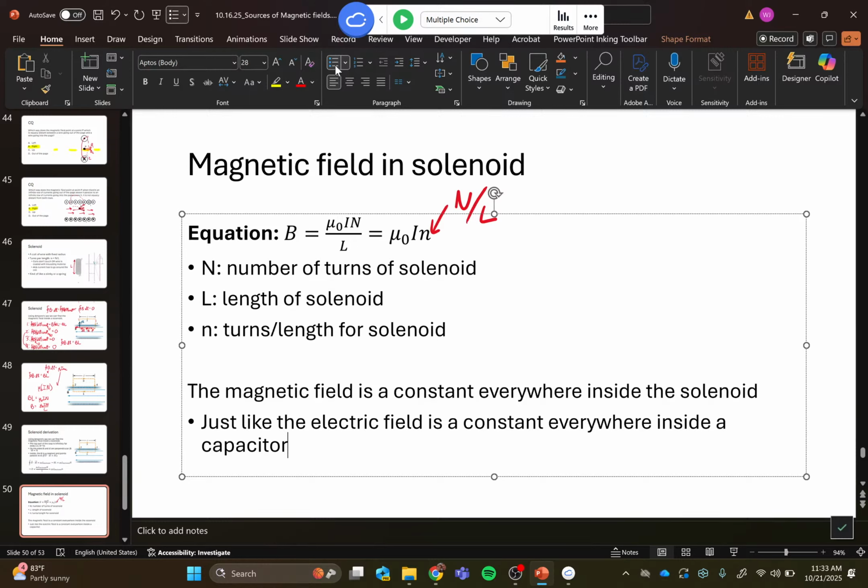Correct. If you all look at these solenoids, if you want to make a strong magnetic field, you take a bunch of loops of wire and you stack them on top of each other. And that is every single circuit. These solenoids are everywhere. Electric motors, it's a bunch of solenoids, a bunch of wires. How do you make it really strong? We're talking hundreds to thousands of loops of wire here. And these really thin wires, now there's limitations. You need a thick enough wire that the current can actually flow through it without getting the wire too hot. Generally not too big of a problem though. But generally you want a bunch of loops of wire.